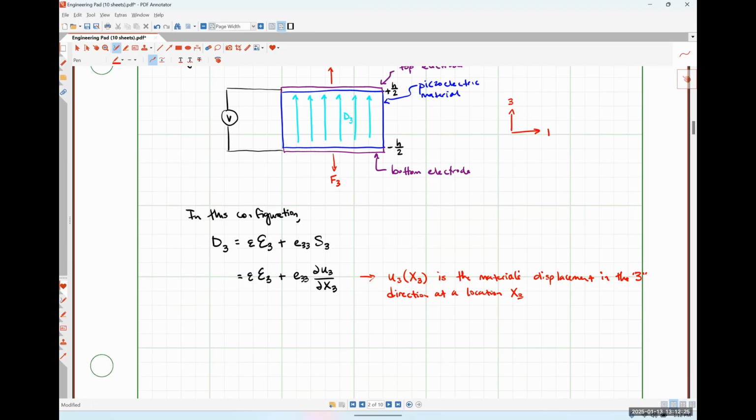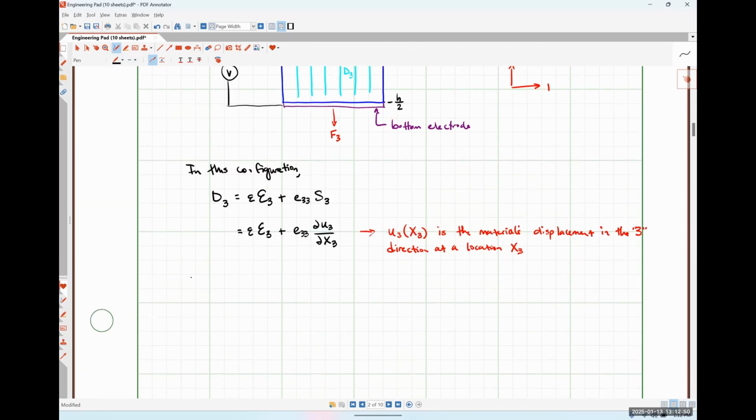per unit of that direction, which is exactly what strain is supposed to be, right? Strain, we've measured it previously in this class as the fractional change in length over the length of the beam. Same thing here. This is the change in displacement along a particular direction. So nothing different than what we've done. So what we're going to do now is integrate across our transducer. Okay.